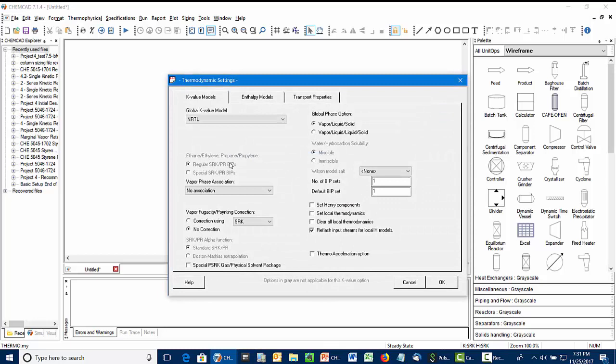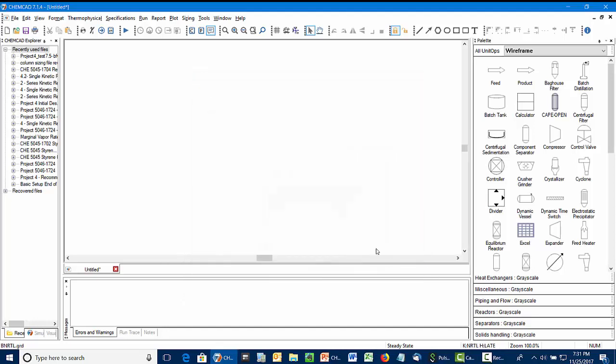And just reviewing the thermodynamic settings quickly, there's nothing that we need to adjust here. We're not going to get liquid-liquid phase splitting because water and glycerin are miscible in all proportions. And we're at a pretty low pressure range. So we'll take OK for these.